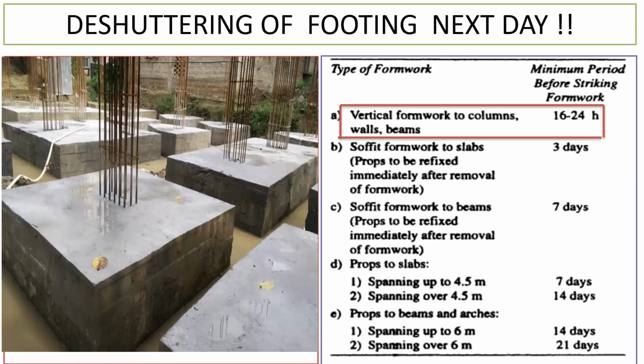That is why we say concrete is going to take 28 days to gain the strength that we have put in for. For example, if M20 grade is used, that M20, that is M stands for mix, the 20 is the strength that is required. So that 20 strength is going to achieve only after 28 days.